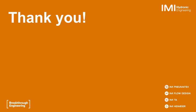All right, thank you. This one says, what is the maximum number of balancing valves you recommend before you have a branch valve, and do you recommend a branch valve for each floor on a multi-floor building? Yeah, that's a good question, because usually we want to avoid that fishbone project. You know, when you have a main pipe and all of the balancing valves are hanging from that main pipe, right? The balancing starts to become a nightmare.